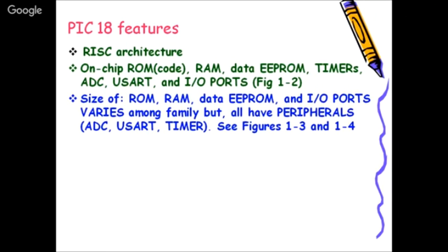Whereas in case of PIC, you will see that it has got 4 kilobytes of RAM, and out of them, obviously, 256 bytes are reserved for your special function registers. So in RAM space, there are basically two kinds of registers: SFRs and GPRs, the general purpose registers. So the file registers of the RAM comprise general purpose registers and special function registers. Every controller will have special function registers for sure. Your general purpose register memory may be restricted.